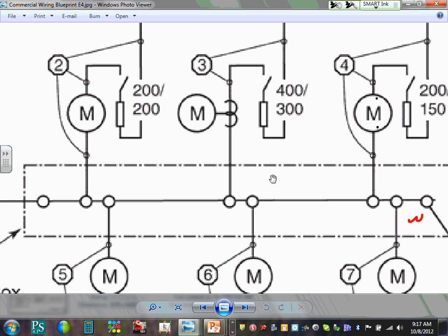So what they do is they take a CT, a sensor, and then they feed a meter. So the 400 amp here will be seen as 5 amps. Because if you put all the 400 amp through the meter, you burn it. CT is a current transformer. They use a current transformer, guys, that steps the 400 amp down to 5 amps, and proportionally, if this